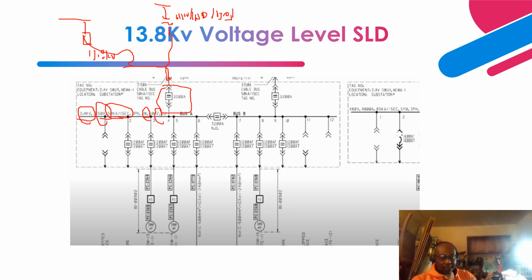of the bus. Basically, this is determined initially as part of the system planning process, where system studies are performed, load flow, short circuit studies. Based on the simulation, they are supposed to do the equipment selection parameters, and it should be about 15% above what their system studies are providing them.